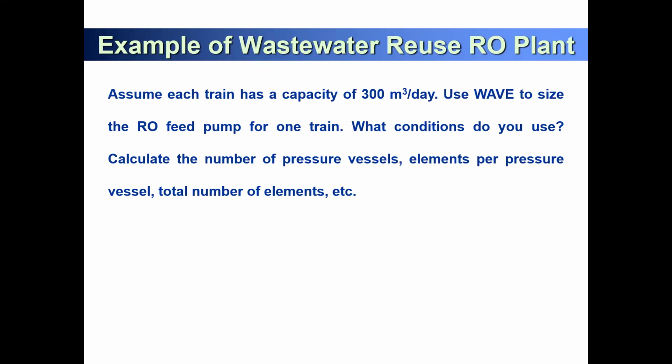But if you recover 90% of the feed water, your final wastewater brine is almost 10 to 15 grams per liter. So why can't we increase more, like 35 grams per liter, 70 grams per liter? So why can we not do this? Why can't we apply 70 bars, 80 bars for wastewater reuse to increase to almost 95%, 98% of recovery?